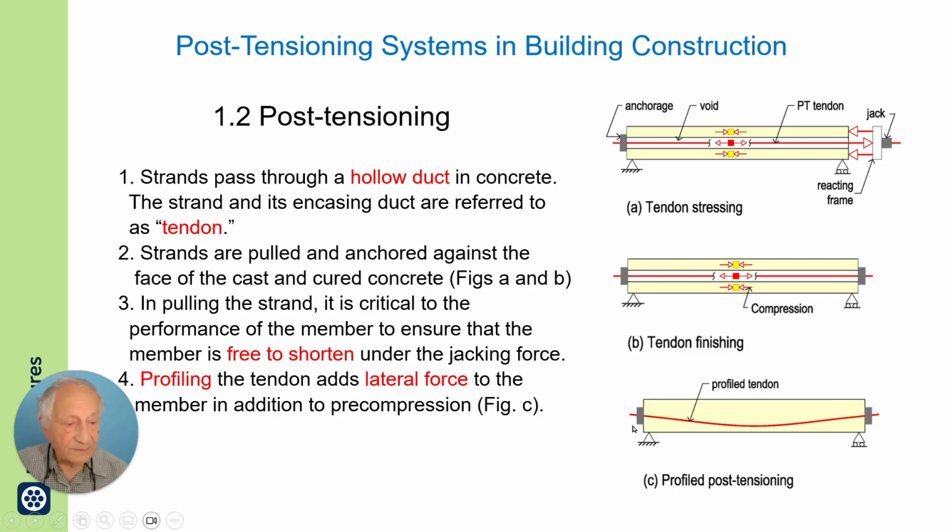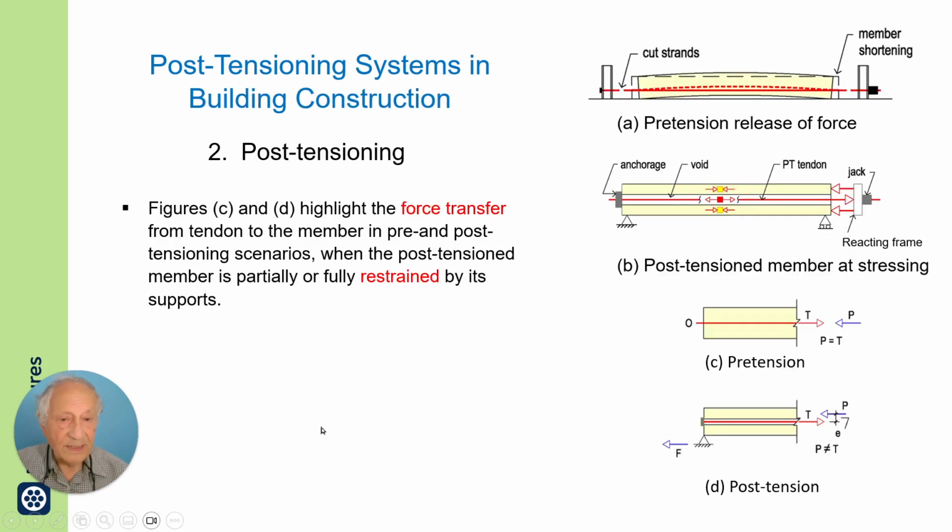Profiling the tendon, as I have shown here on the right, adds lateral forces, up and down forces, in addition to the pre-compression, and the profile can be selected to be beneficial to the in-place performance of the member.